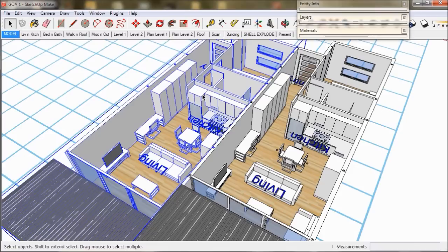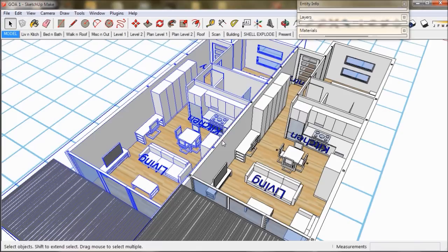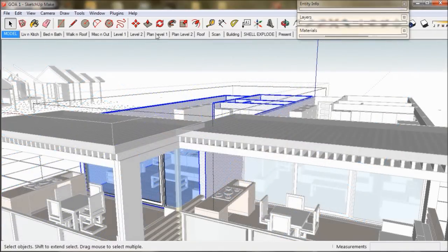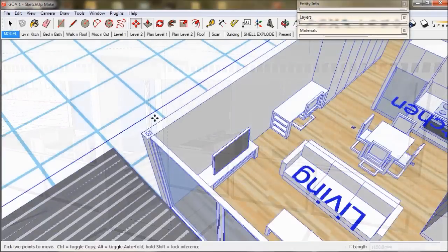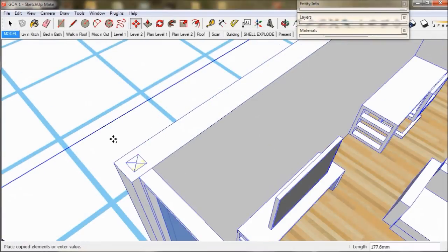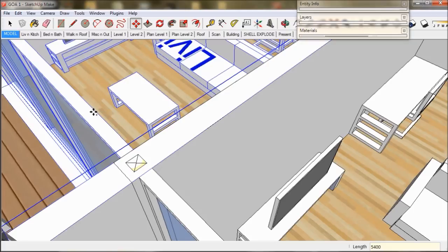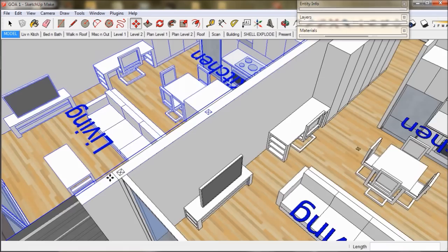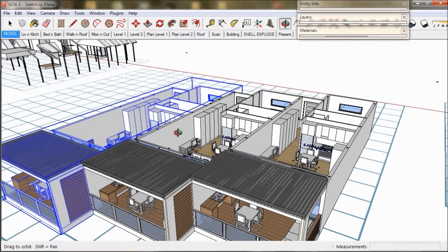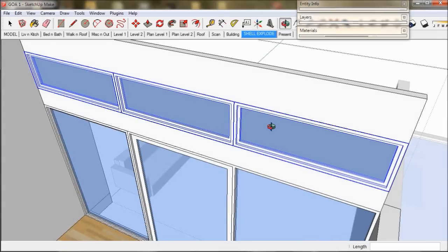Now we select the new apartment and choose Make Unique, and we call it Inner Type. So now I'm just going to drag across a screen wall for the inner type to separate the balconies. And now create another copy of the inner type apartment using the same staggered pattern. Now we'll move on to the outer type apartment, which will have the roof.